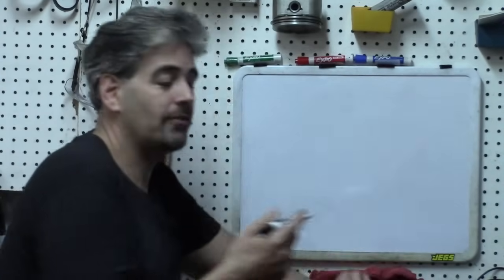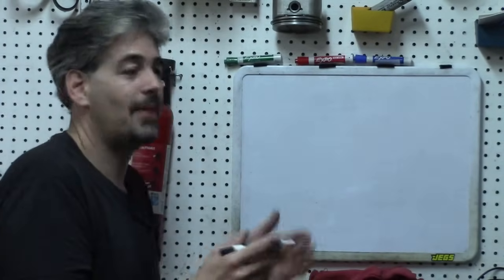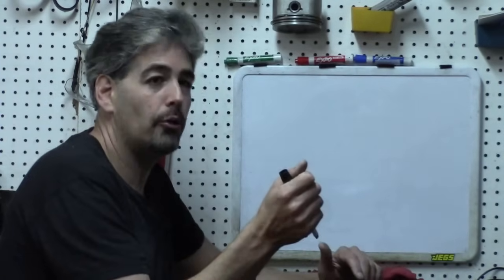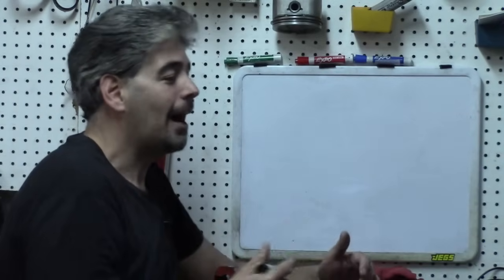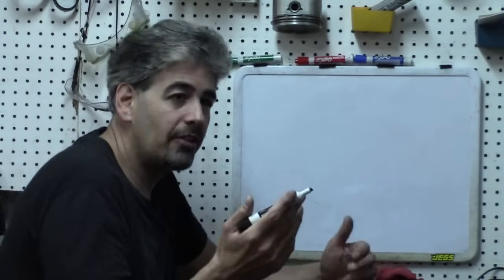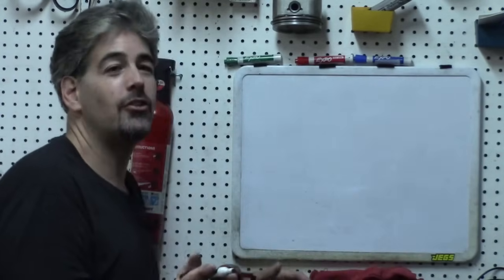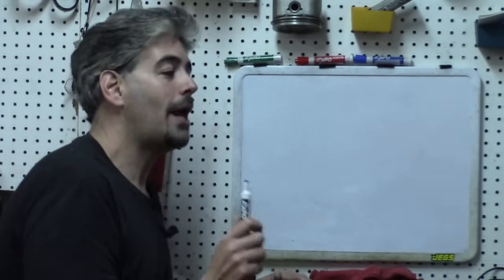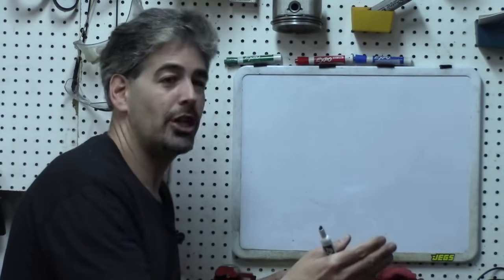A case in point: very commonly people who diagnose a fuel pressure problem look in the flow guide and it tells them at some point, remove the vacuum hose from the regulator, and then look for a fuel pressure change. Is it supposed to increase or is it supposed to decrease? Well, you have to look up and remember. You won't have to do that, I promise. For the rest of your life, you will always know what happens when you remove the vacuum hose from a fuel pressure regulator and what you should expect.